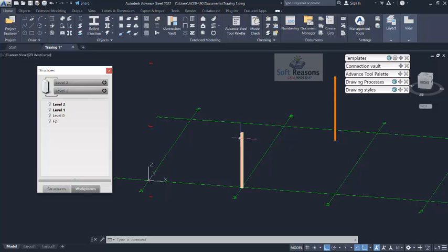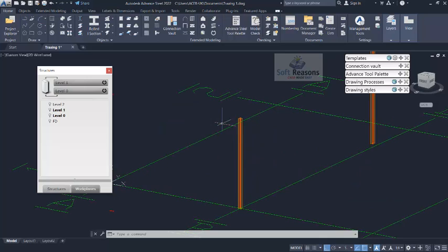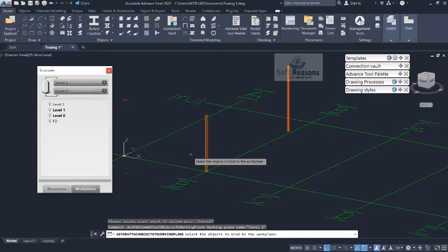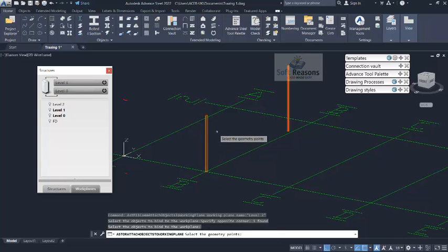Now you can extend the top constraint, which is level 1 right here, to the top constraint level 2. What you just have to do is place your cursor on level 2 right here and then right click in this drop down, select attach. Once you select attach, you will select the element, which is the steel columns right there, and right click.